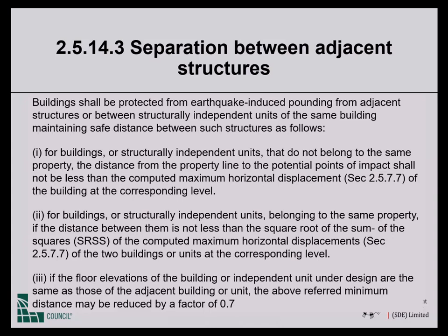In the second case, when the two structures belong to the same property, we allow a shorter separation distance. The idea being that in the second case, when both properties presumably belong to the same owner, we would allow the two buildings to touch, but we do not want unacceptable damage.